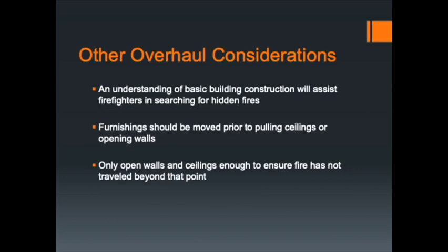So during overhaul, please again just understand building construction, understand how the building is built. So this refers back to your building construction section of Truck Pert, also back to your basics program. Understand that the more the fire burns within a sealed space, the more heat you're going to have in that space. So if you never open it up, never get the heat out, the heat's going to continue to increase, and that's generally where rekindles occur. Say there was a spot in the building that nobody opened up, the fire just lays there for a while, and then what you think was just smoke or steam at one point turns into visible fire after a few hours.